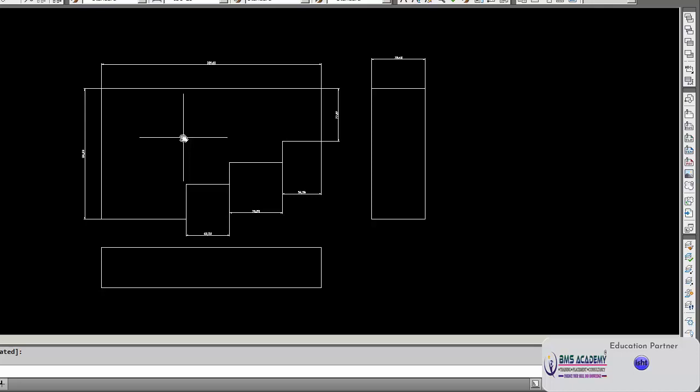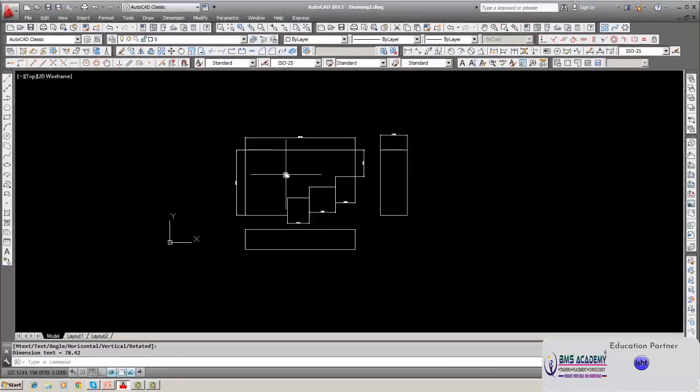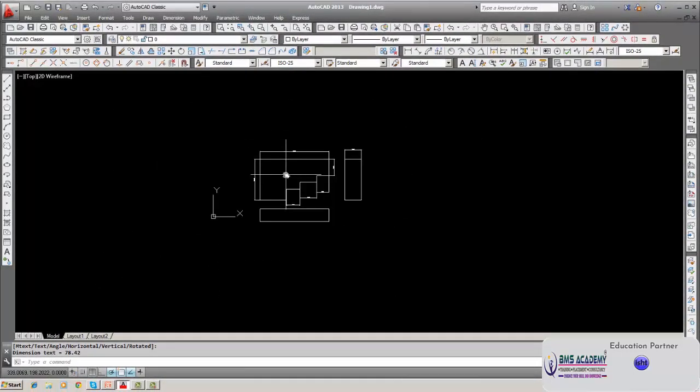If you print the drawing and measure the size on the drawing divided by the actual size of the object, that is the scale factor, expressed as a fraction. For example, 1:4. Here the actual size of the object is 4, where 1 is the size on the drawing. This is how the scale factor works. So I will write here.